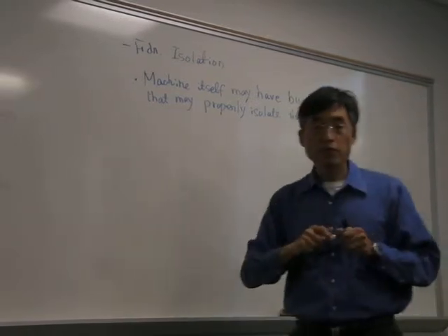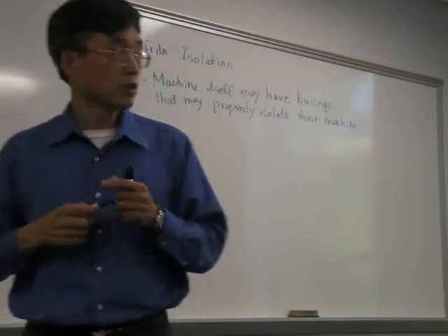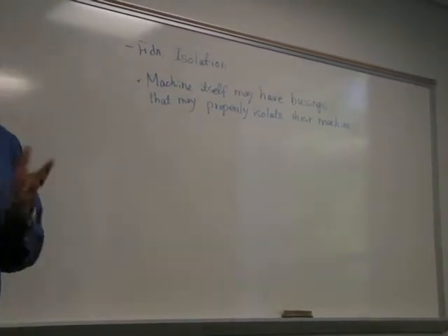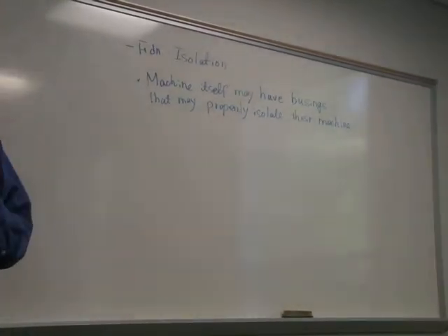One of the good examples of using rubber bushings so that vibration does not propagate. I should not say it does not propagate, I should say it can reduce the vibration substantially. Is vehicle engines. We know vehicle engines vibrate, but when you are in the cabin, you don't feel that much vibration.